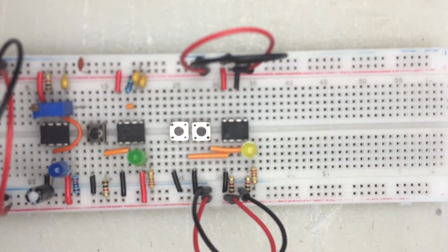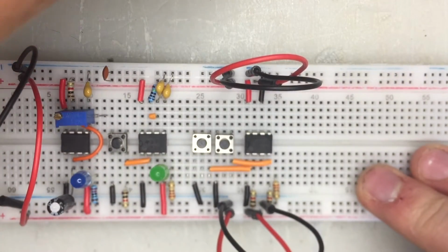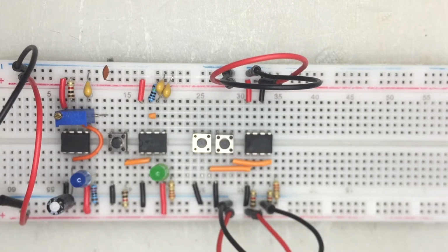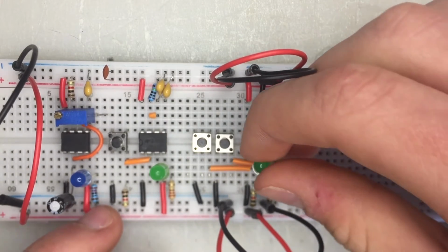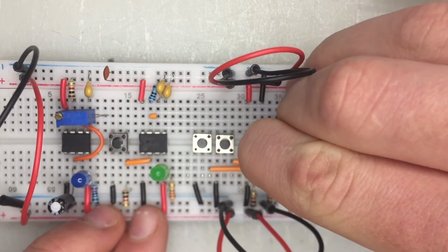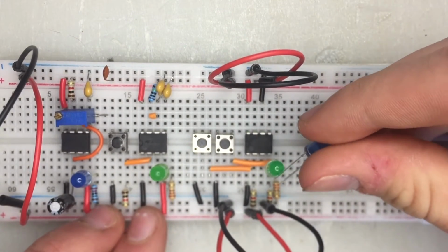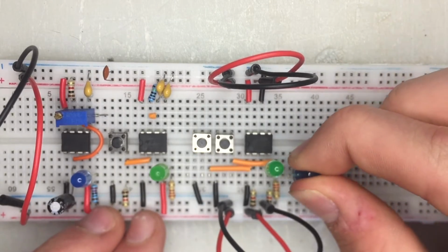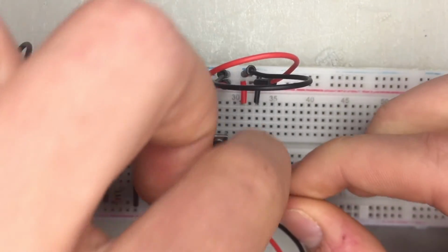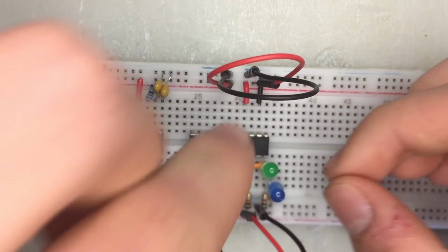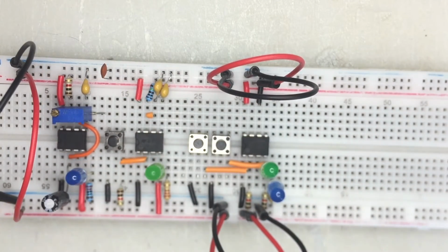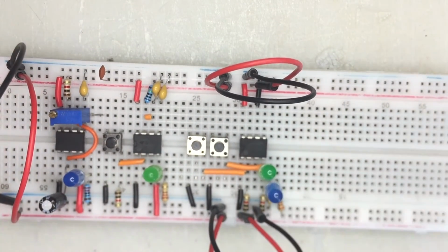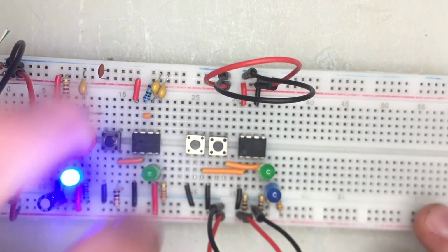But one thing I do want to change about this is connect up 2 LEDs where one of the anodes is connected to the output but the cathode is connected to ground through a 220 ohm current limiting resistor, just like we had, but the other one's cathode is connected to the output and the anode is connected to 5 volts with a 220 ohm current limiting resistor, so that in each state of the bistable circuit there will always be one LED on. And now I've got that set up, I'll plug in power and this should work.